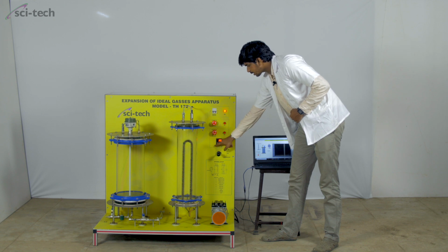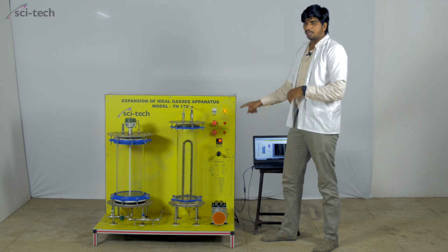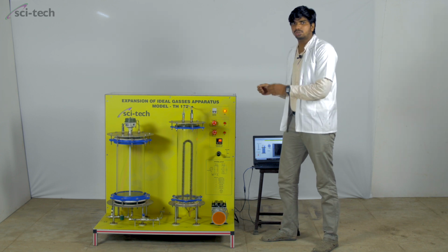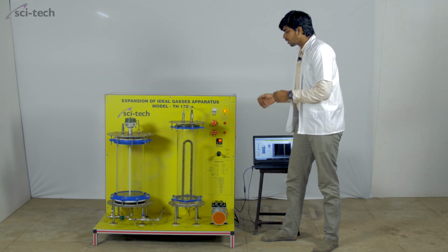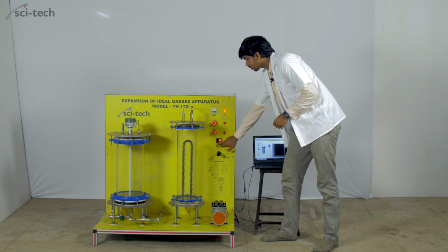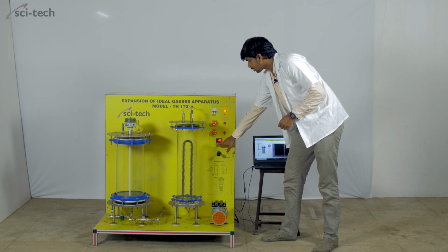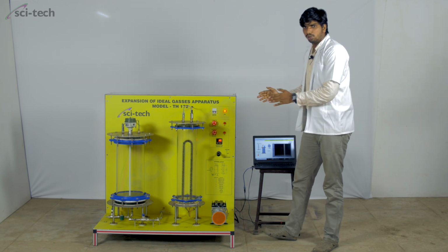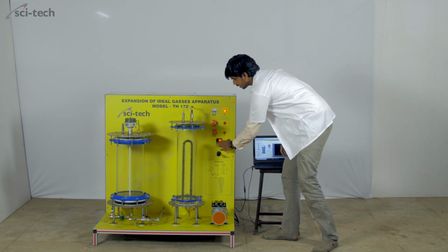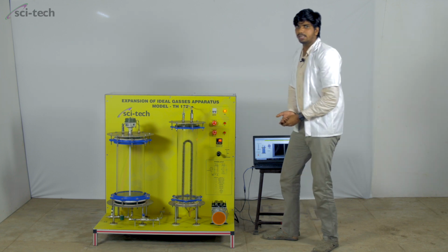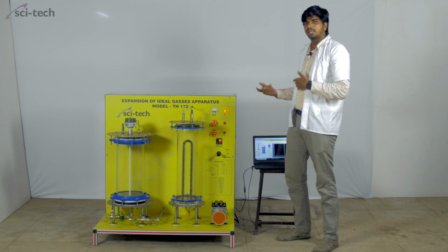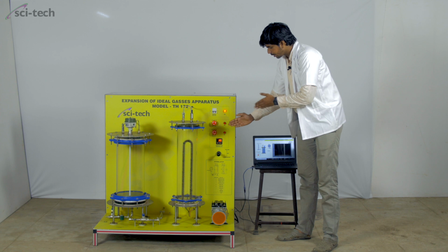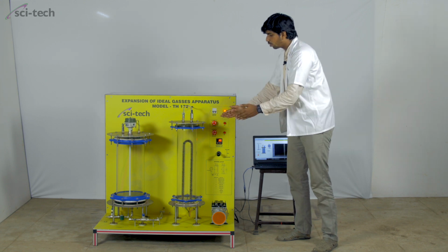Here we have a temperature controller, which I have already explained. The purpose of this temperature controller is to set the maximum temperature you want for safety purposes. For safety, I have already set the temperature at around 100 degrees Celsius, and with the help of these keypads you can also set 100 degrees, 120 degrees, 130 degrees, for example. After performing this, you can check the temperature controller setting value.